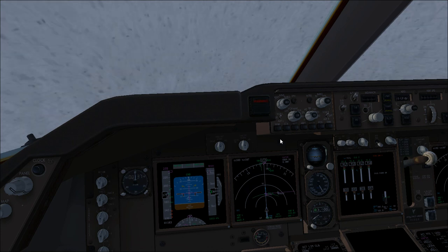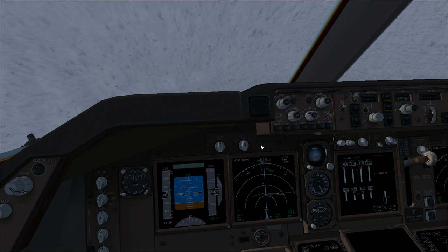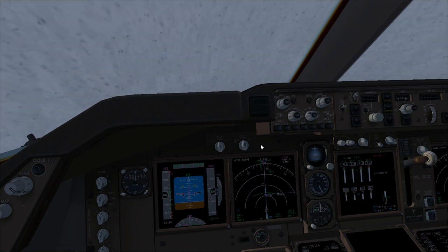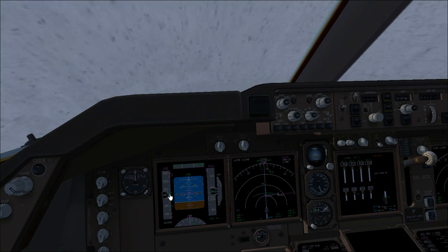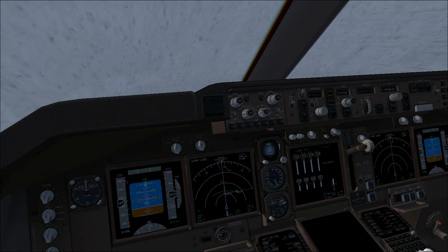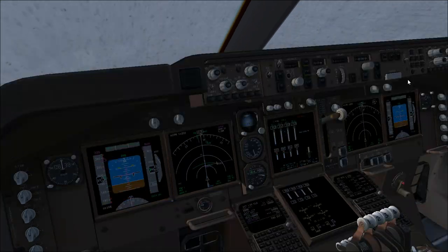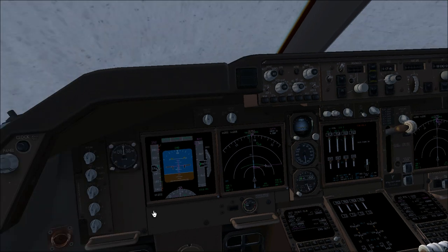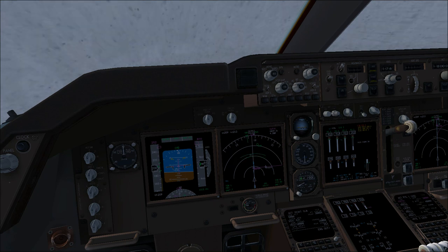And during the acceleration, we now have the fire warning, as we said before, so we can clear the alarm and take the QRH for the procedure. First of all, wait for flaps 5, just to clear the flaps 5. We can select engine display to see what's happening. We have the process standard, so we are fine. Selecting flaps 5 now, and the first point for the QRH fire warning procedure is thrust lever to idle and fuel control to cutoff.